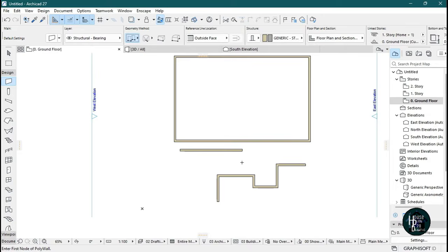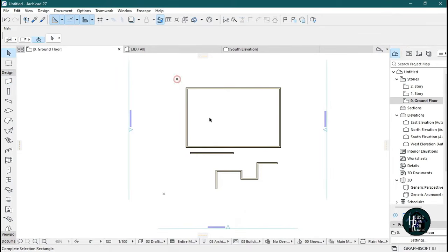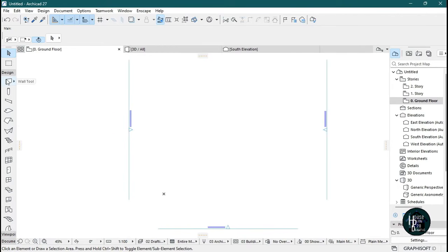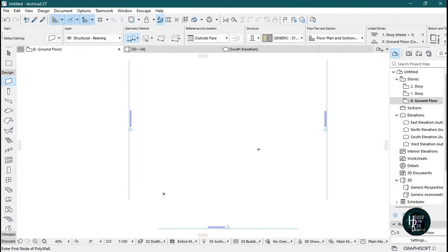Okay, so without any further ado, I'm just going to delete this and let's get into the business again. So click on the wall tool. Now I want you to select here, drag it up, and if you look at the distance reading, I want you to give a distance of 15,625. Click enter and click enter again. Okay, so you've made a particular wall like this.